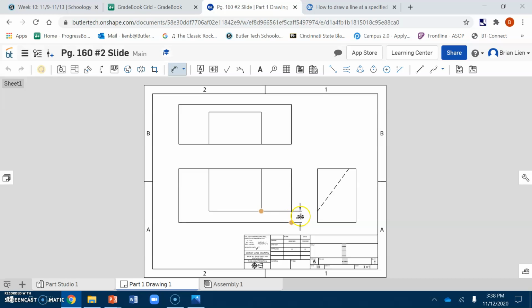That's about 3/8 out here. And then I want this point and that point. Come out about here and watch where you put your number. You don't want it down here. So probably about there. So there's those two. I need the dimension from this point to that point. Coming out here. Notice I'm in line with the one below, so that's what we want. Keep everything in line.